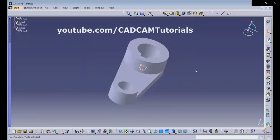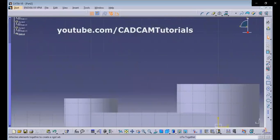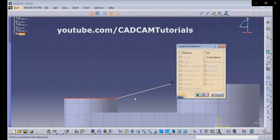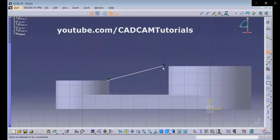So select that plane, sketch, then create one line here. Line, then select the corner, then select this line by pressing Ctrl, then constraint define in dialog box, coincidence. Okay. Again this line and this line, constraint, this point and line actually, and coincidence. Okay. Then give the constraint from this point to this axis.